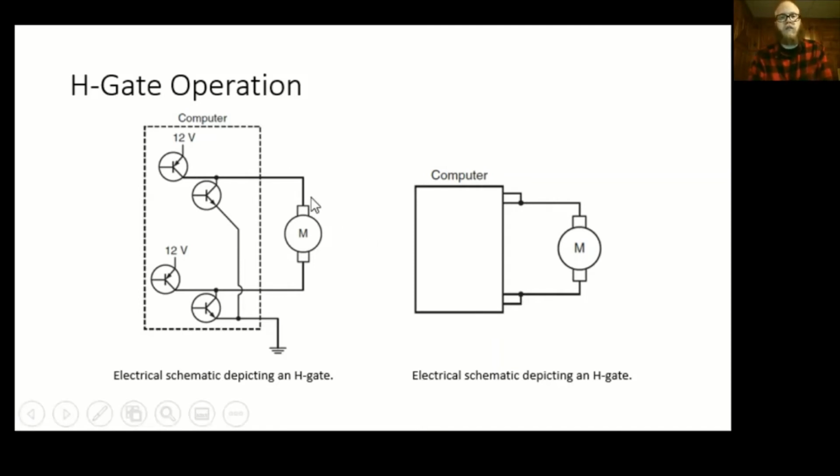Maybe it just gets 12 volts on one wire coming into it. Maybe this is connected to another computer and we could go in with our scan tool and see a request. Yes, it wants it to roll down. Okay, we're seeing that on our PID. Then inside of the door panel, I would check to see, well, let's see if I can just disconnect this connector from the computer, and I'll put power and ground. Did it go up or down?